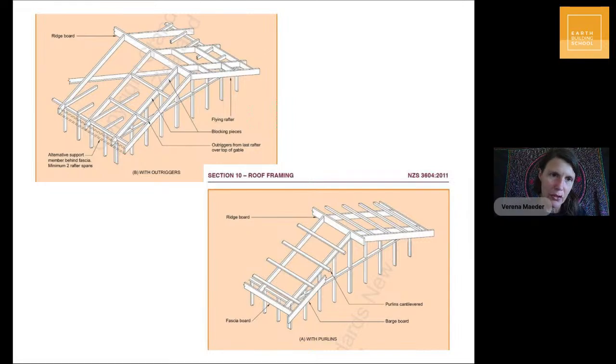Here, I'm just showing you a couple of other things, especially for the earth buildings, but roof overhangs are good for any type of building because they allow you to fine-tune how much summer sun comes in and so forth. They will also protect your walls from excessive rain.